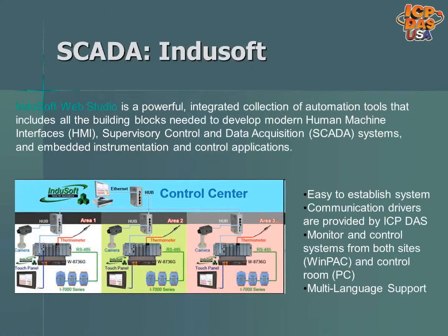SCADA is supervisory control and data acquisition. SCADA software runs on a PC and allows you to interface with various equipment like data acquisition modules, PACs, programmable automation controllers, PLCs, programmable logic controllers, embedded controllers, and instrumentation devices. It comes with a graphic library, so you can use it to create a visual user interface that represents real applications. They also support scripting, so you can implement some control through basic programming commands. They support multi-level user management for security. Different users can have different permission levels.